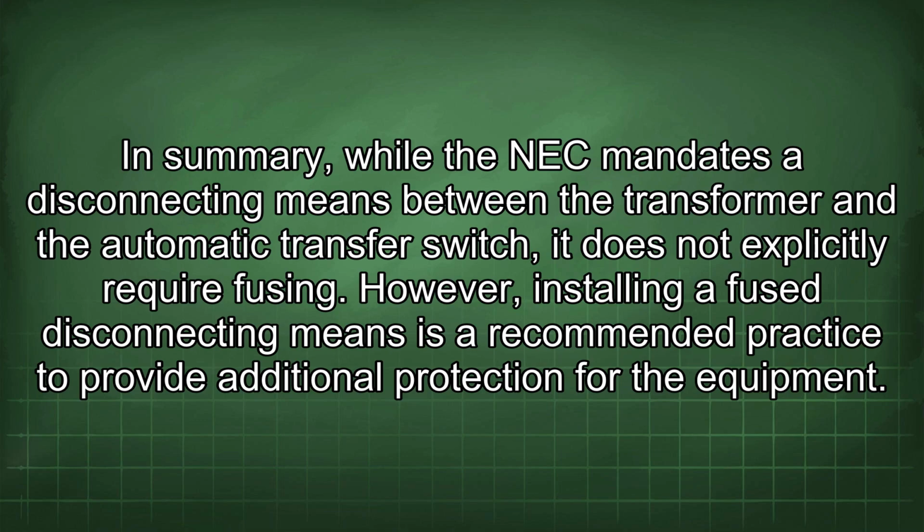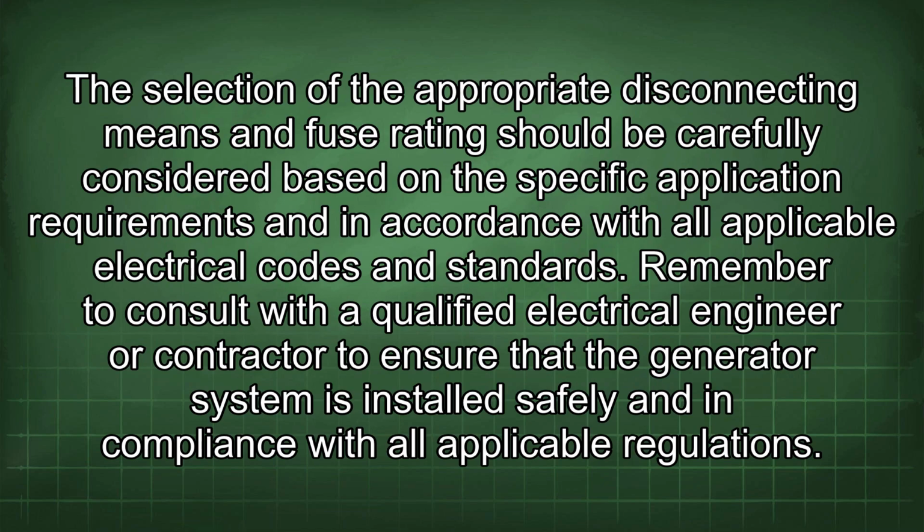In summary, while the NEC mandates a disconnecting means between the transformer and the automatic transfer switch, it does not explicitly require fusing. However, installing a fused disconnecting means is a recommended practice to provide additional protection for the equipment. The selection of the appropriate disconnecting means and fuse rating should be carefully considered based on the specific application requirements and in accordance with all applicable electrical codes and standards.